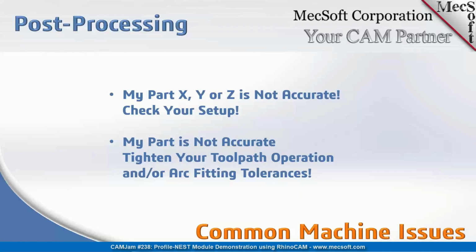Now, there are other issues. Another group of issues that we see a lot has to do with arcs and how arcs are displayed on your controller. If you have a backplot display on your controller, it will look at the file and show the G code graphically on your controller.